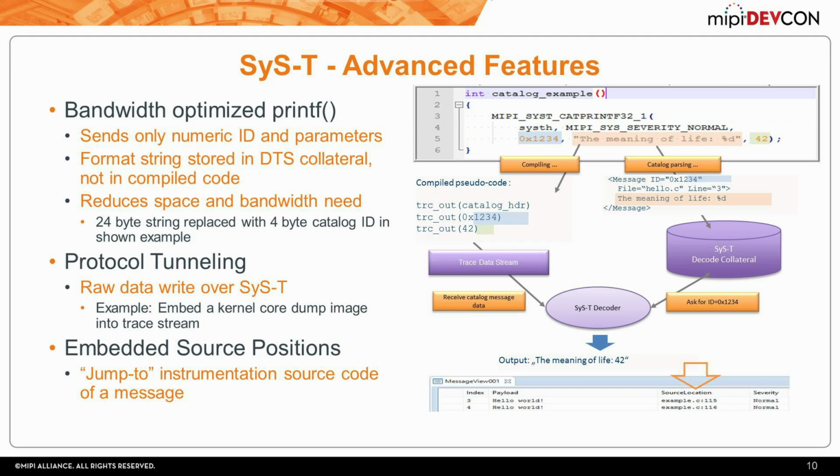The catch is that printf comes with a cost. It's quite an expensive API because you need to store all that information on the device, and you need to parse this format string, create the output string, and send that data. So it's both compute and space intensive and may not be suitable for small devices or controllers. With SyS-T, there's a functionality that is almost like printf, but comes with a much reduced cost.